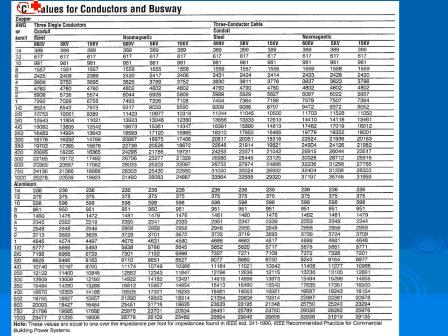I always tell them, without getting too technical, guys, there's an advantage and disadvantage of being far away from the service. When you have a panel 300 feet away from the service, what's the disadvantage? Everybody knows it. Line drop, voltage drop, that's a disadvantage. What's the advantage of being far away from the service? Short circuit. The short circuit will be choked by the impedance of the cable.